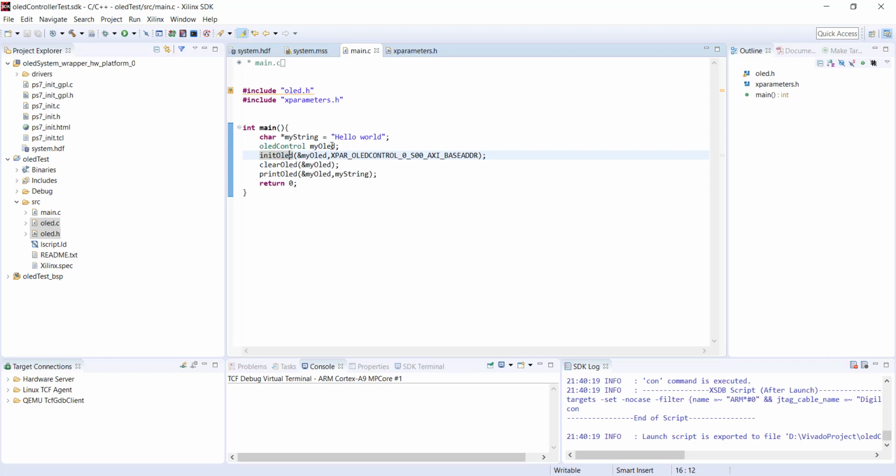So I guess after this tutorial you have a better idea about developing an IP core. You will always develop your core logic first. You will test it, simulate it, and even test on hardware sometimes to make sure it is working fine. Then you create your IP template, then integrate this core logic with the IP template with the help of the internal registers, and you connect them accordingly, and then you write your driver. Okay, so that's it. Thank you.